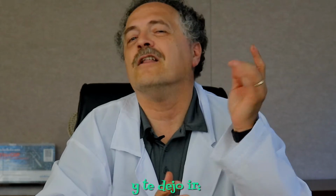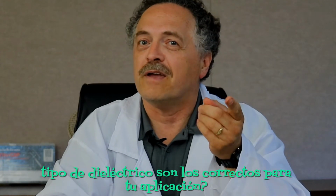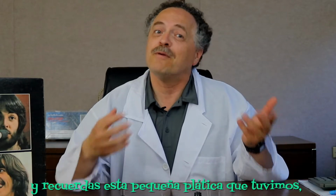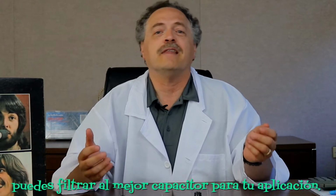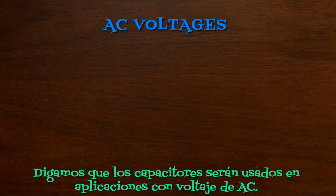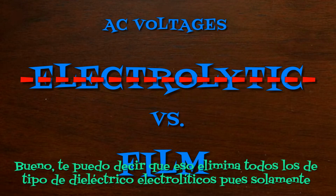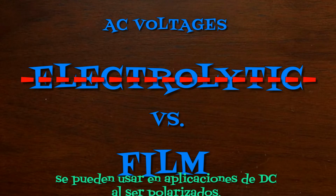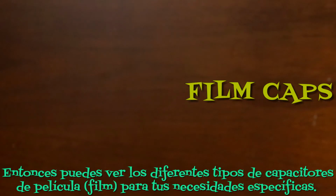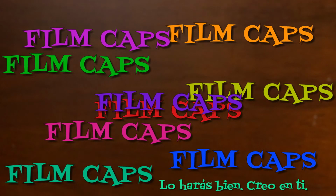One more thing, then I'll let you go. How do you know which capacitor and dielectric type are right for your application? I'm glad you asked. Once you know the specifics of your application and you remember this little talk we had, you can whittle down to the cap that's best for your application. Let's say the caps are being used in some AC voltage applications. Well, right away you can eliminate all the electrolytic dielectric caps, since they can only be used for DC applications since they are polarized. That leaves film caps. Then you look at the different types of film caps for your specific needs. You'll get it right. I believe in you.